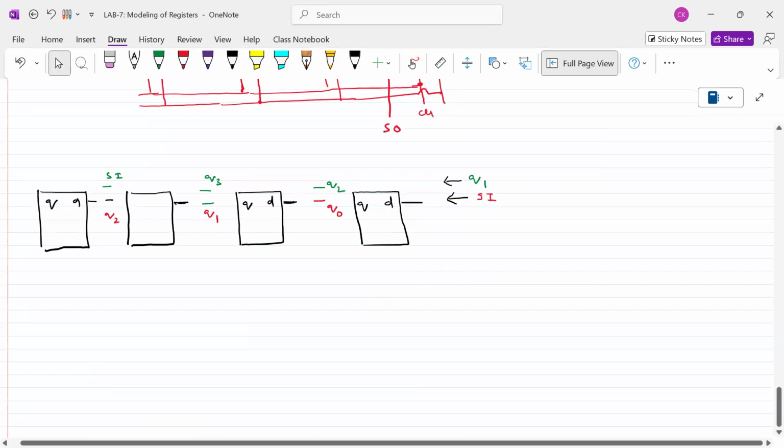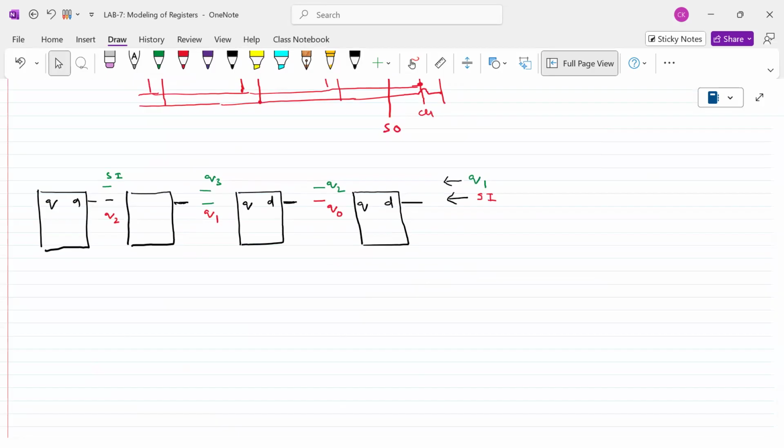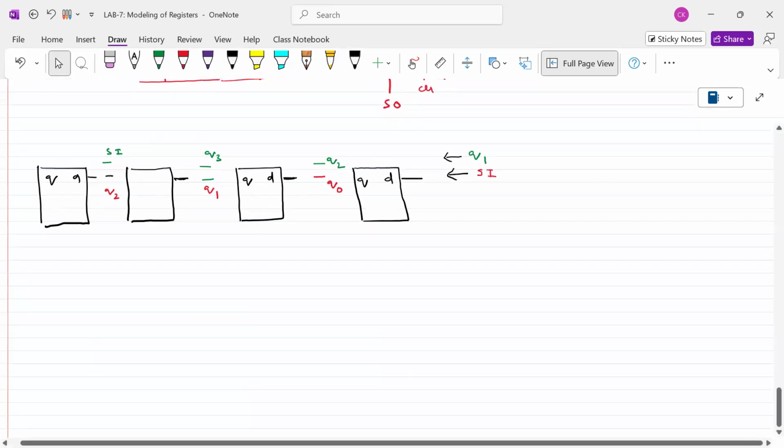Now the question is that we want to operate only one shifting. The right shift operation you can do it, or the left shift operation you have to do it. That means you have to choose only one input out of these two inputs as an output. Therefore, what device is required for this? If you have two inputs, and at a time only one input has to go as an output, then what kind of device is required? Multiplexer is required. What is the size of the multiplexer in this case? A 2 by 1 multiplexer is enough. We are going to have one multiplexer here.